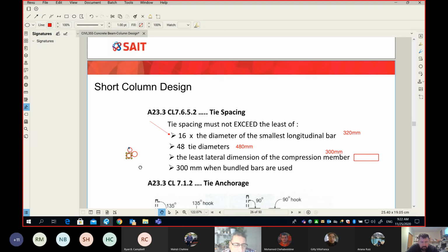And so we allow zero spacing. We put them close to each other, right? And this is called the bundled bar. This is not really very typical; we always leave a spacing. We only need it if we have very, very heavy reinforcement. Let's say you were working on a bridge girder, so you bundle the bars together. So please ignore this one in my class.